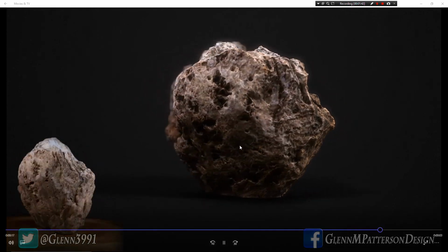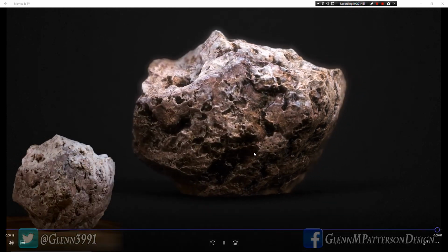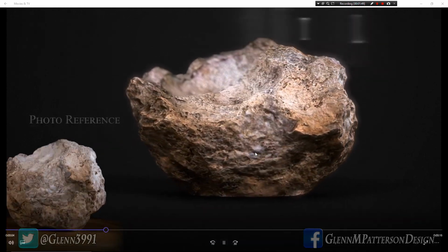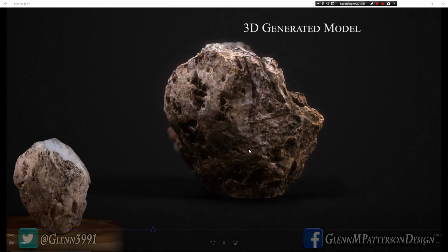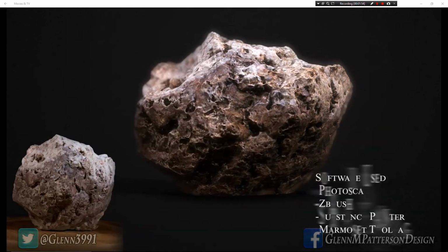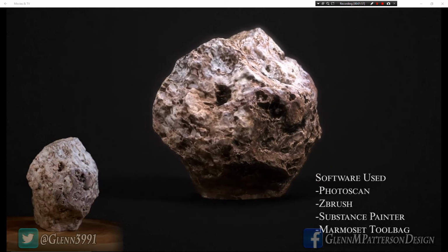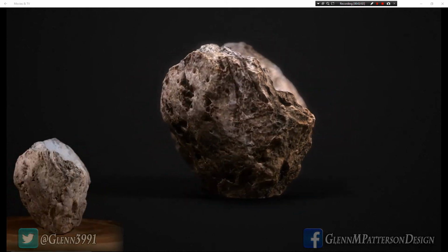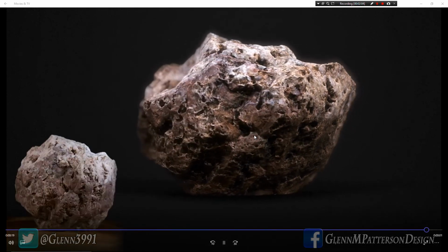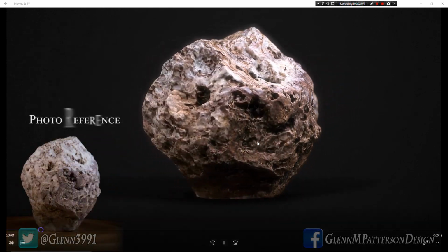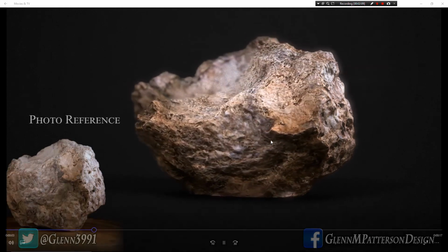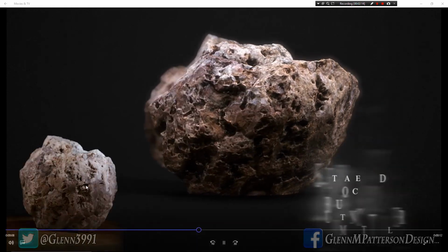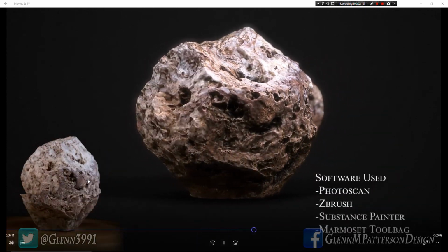One don't would be don't do shiny objects, anything reflective, anything metallic, anything that's throwing around different reflections as you look at it from different angles. Because that will cause errors and the computer just will not quite understand what it's looking at. So try to avoid that, which we will today. We're just going to use a flat rock that's not really shiny.